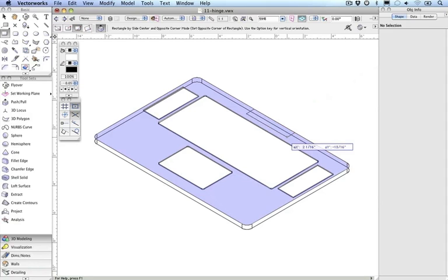of an inch. With the current mode we are using to draw the rectangle, we need to input half of this width. Press the Tab key to enter the Delta X field and input 11 3/8 divided by 2. Press the Tab key once more to enter the Delta Y field and put -1/2 inch, then press the Enter key. Now, click in the drawing to set the rectangle.